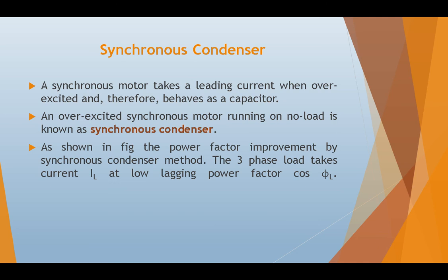So, synchronous condenser. We know that a synchronous motor takes a leading current when over-excited and therefore behaves as a capacitor.